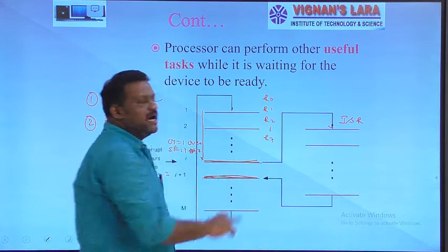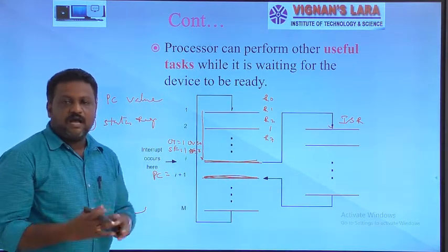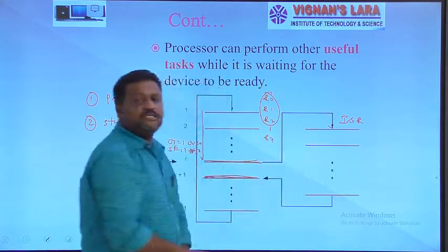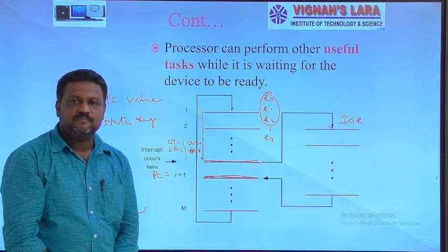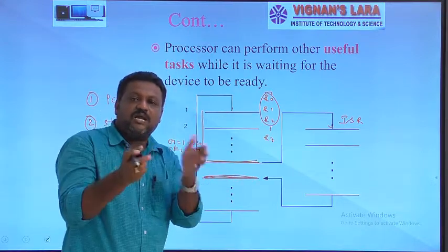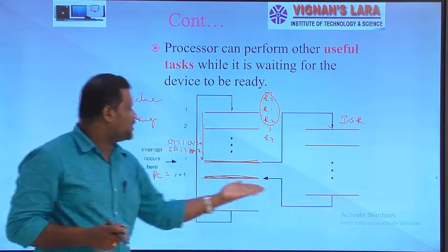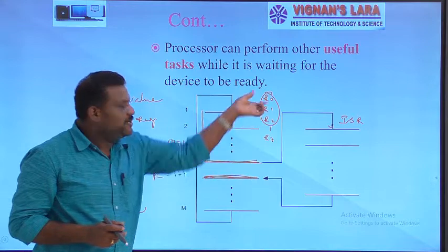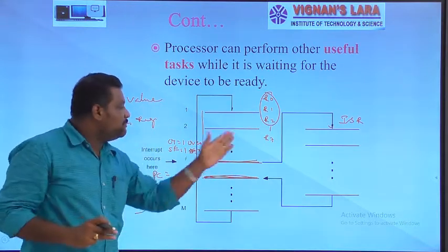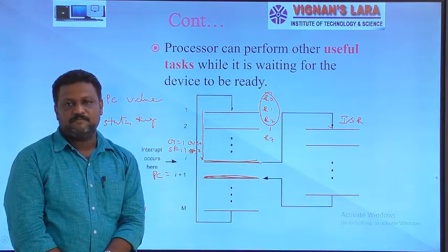I use up to R7. Out of these 8 registers, I may go and use these 3 registers in this ISR execution also. If I use these 3 registers in this ISR execution, what happens is, if I come back after execution of this ISR to the previous stopped program, these registers may not have the same value that previously existed before shifting execution from this program to the interrupt service routine.